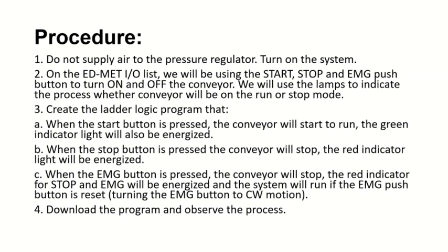Create a logic program such that when the start button is pressed, the conveyor will start to run. The green indicator light will also be energized. When the stop button is pressed, the conveyor will stop. The red indicator light will be energized.